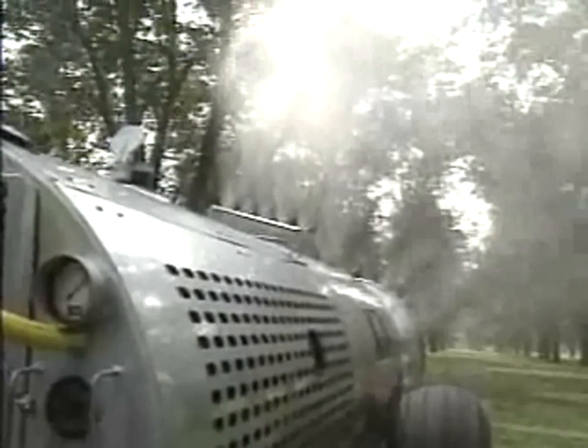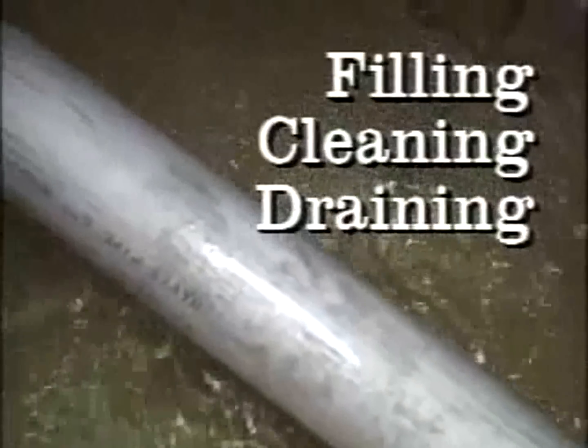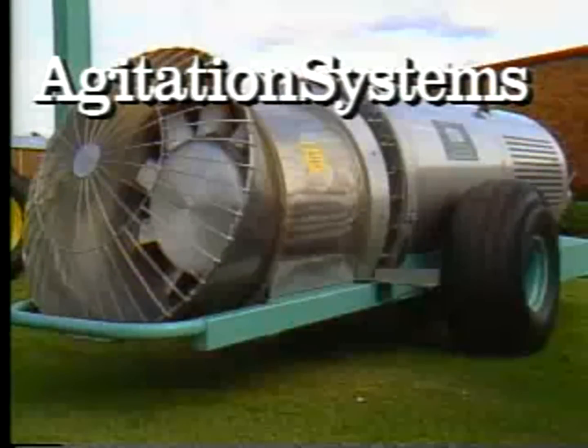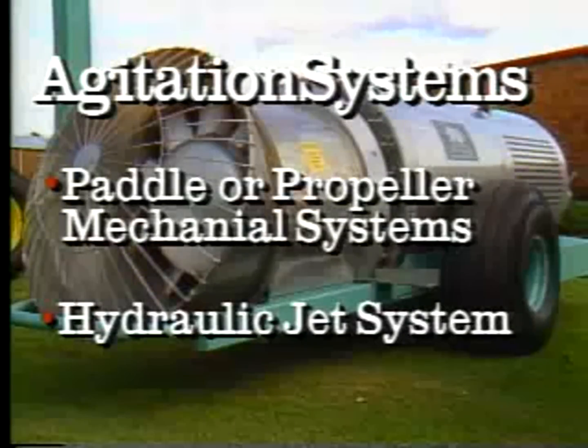This is a typical air blast sprayer. The tank should be corrosion resistant and designed for easy filling, cleaning, and draining. Agitation in the tank should be sufficient to keep all pesticides thoroughly mixed, both when spraying and when the spray nozzles are shut off. There are two types of agitation systems: paddle or propeller type mechanical systems and the hydraulic jet system. Both should keep the pesticide solution thoroughly mixed.